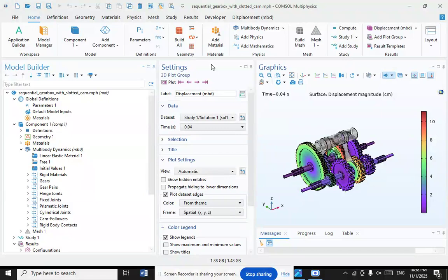It has teeth to fit into the splines on the shaft, forcing that shaft to rotate at the same speed as the gear hub. However, the clutch can move back and forth on the shaft to either engage or disengage the splines. This movement is controlled by a selector fork that is linked to the gear lever. The fork doesn't rotate, so it is attached to a collar ring on the selector. The selector is typically symmetric. It slides between two gears and has a synchromesh and teeth on each side in order to lock either gear